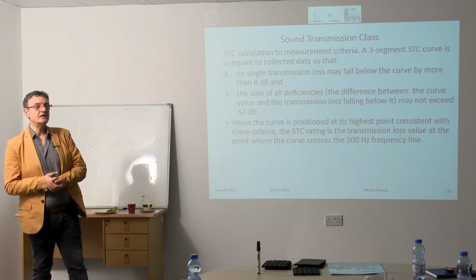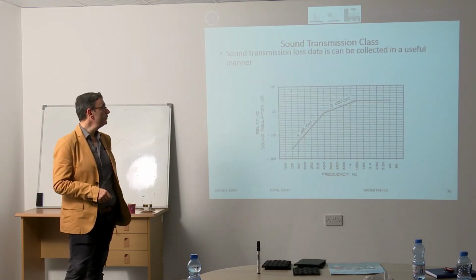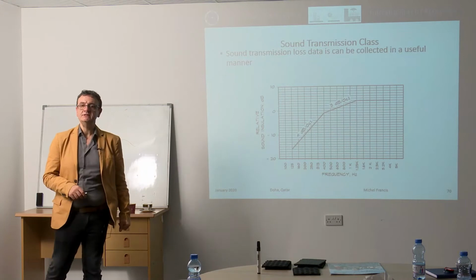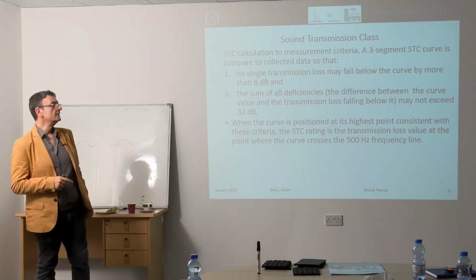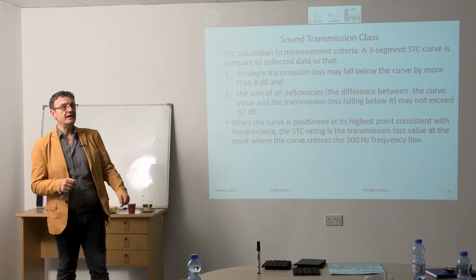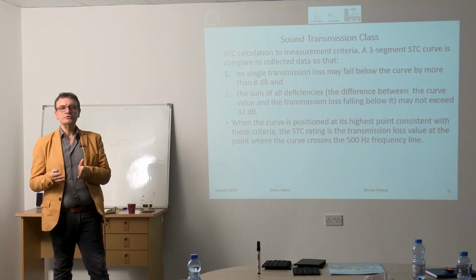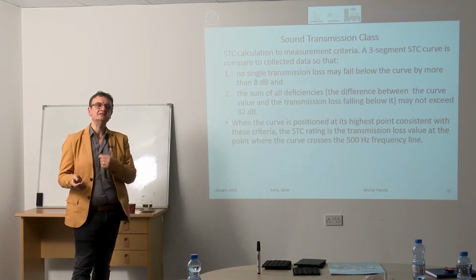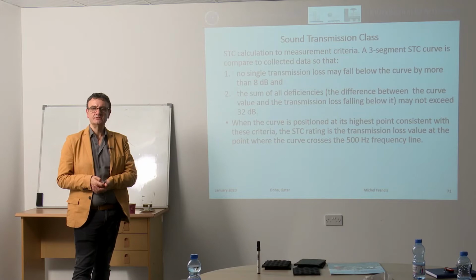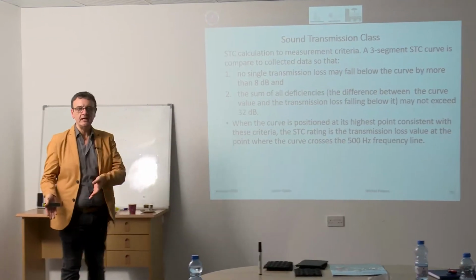Therefore, sound transmission class is not calculated, although you make calculations to find the end result. However, without taking measurements and plotting those measurements here, you cannot find an STC. It's all by test. There is software that mimics the STC rating and can give you an expectation of the STC rating based on the mass law, but those are not real STC, because real STC is based on tests and measurements. So when you see an STC of any material, that means that material has been tested in the lab, and that STC has been found according to those tests.